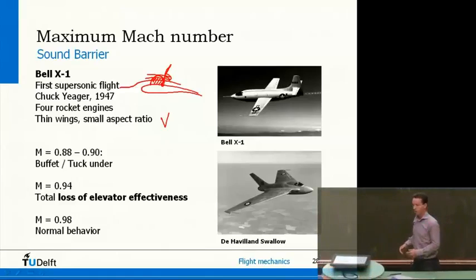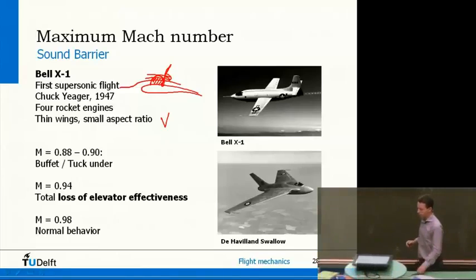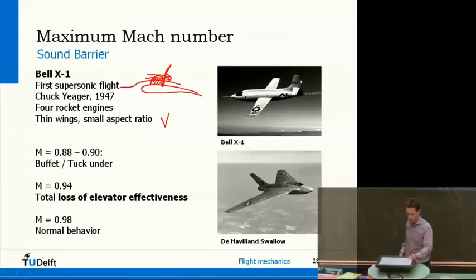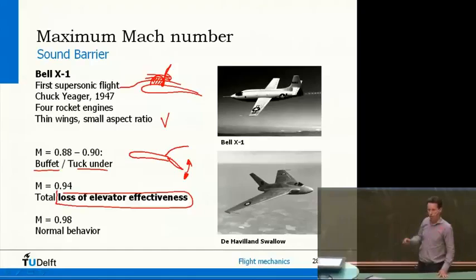But what also happens is that if you start to go very fast, then the point at which the lift is acting on the plane gradually shifts a little bit. So what you will start to feel if you go very fast is buffeting, and the nose might go up, it might go down, simply due to the fact that the lift of the aircraft acts at a different point. But what may be even more important is something else. At the back of the plane you have the elevator, and of course you want to deflect that up and down in order to control yourself. Now, if you fly at very high speeds, then at some point a deflection downwards could actually cause a shock wave over here, which means that in some cases, without going into the details, these Mach effects can make the plane become uncontrollable.